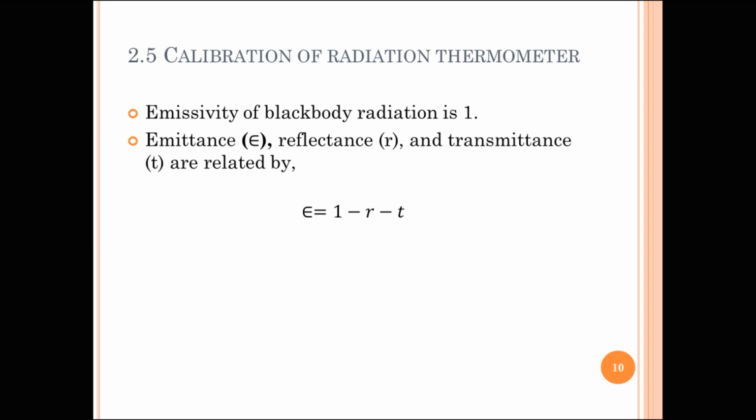When we discuss complete instruments for radiation thermometry, we will find some are designed to measure at one specific wavelength, others for a specific band of wavelengths, and still others for all wavelengths. This wavelength tailoring shapes the instrument's reading to suit a particular class of applications and is accomplished by the designer's choice of detector, lens material, and optical filters.